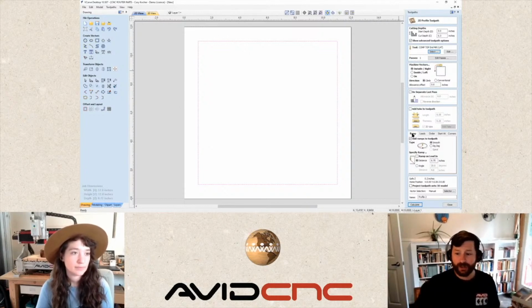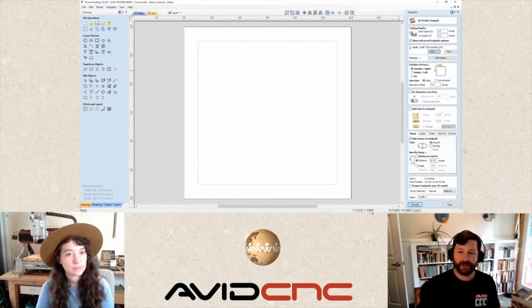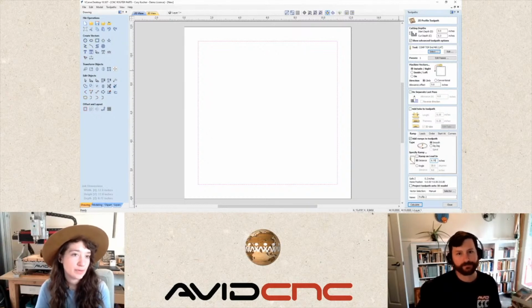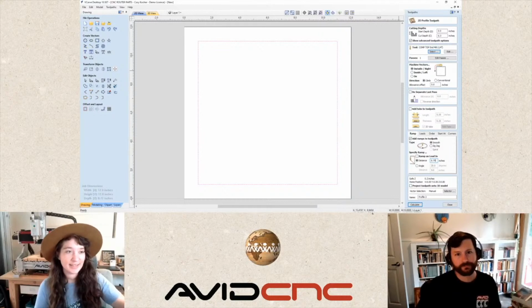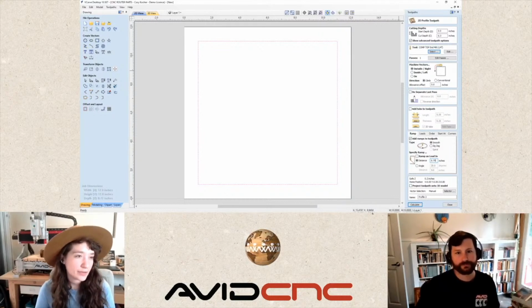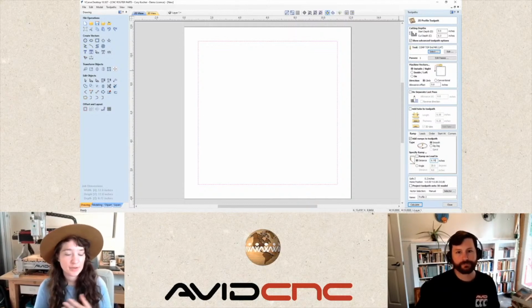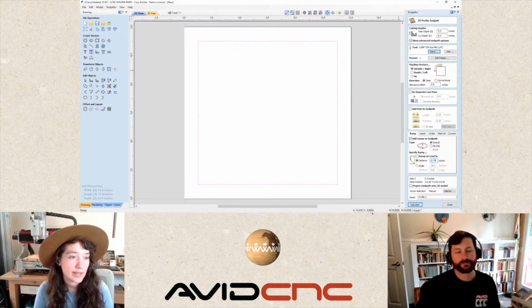And so we're going to have a ramp here. I like a distance somewhere around 3x the tool diameter. It kind of depends on your material blank size, your machine bed. And Sami, what kind of style ramp do you typically pick? I typically reach for the smooth ramp. I just like that easy ramp down into the tool path, and it's a little bit easier on the tool, I think, and it's not changing directions like you would with the zigzag. I know that does also give it more of a lateral cut, so it's kind of preference there.